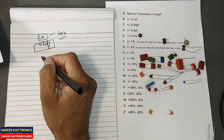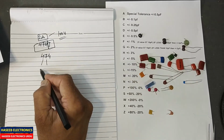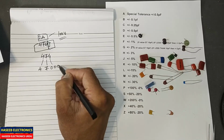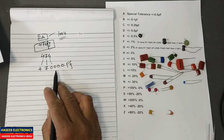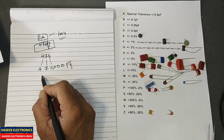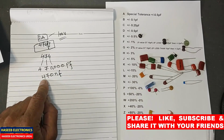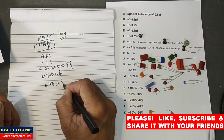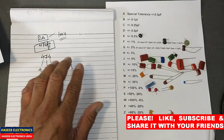Then we have 474. That means 4, 7, we will write it as it is. Then we will put 4 zeros: 1, 2, 3, 4. This is in picofarad. If we want to convert to nano, we will put a dot here. So it is 470 nanofarad. We will divide it by 1000. It is 470 nano, or we can say it is 0.47 microfarad. So in this way we can identify the capacitance value.